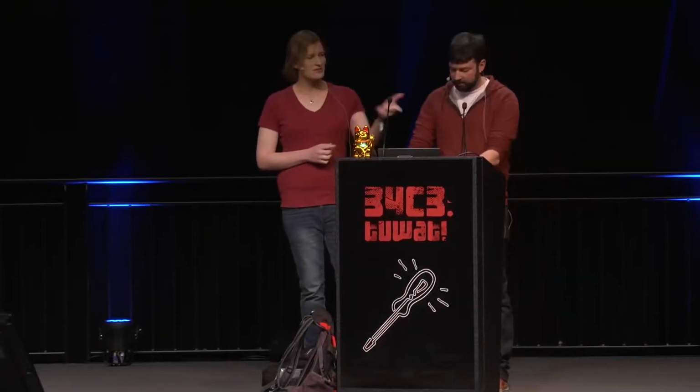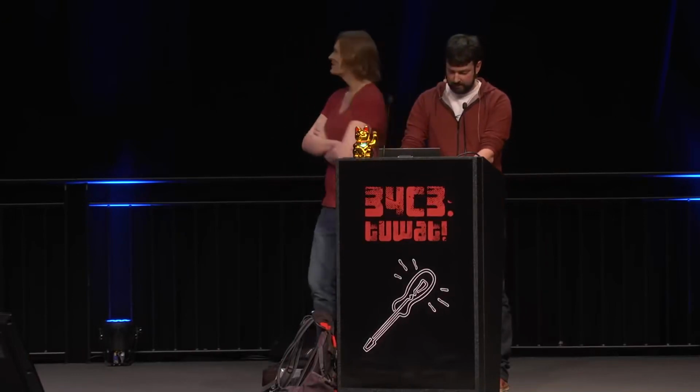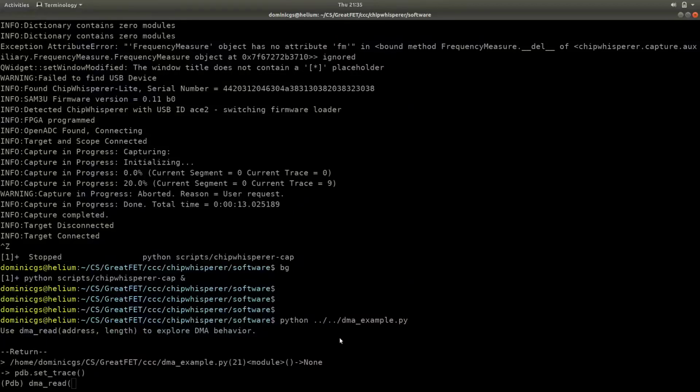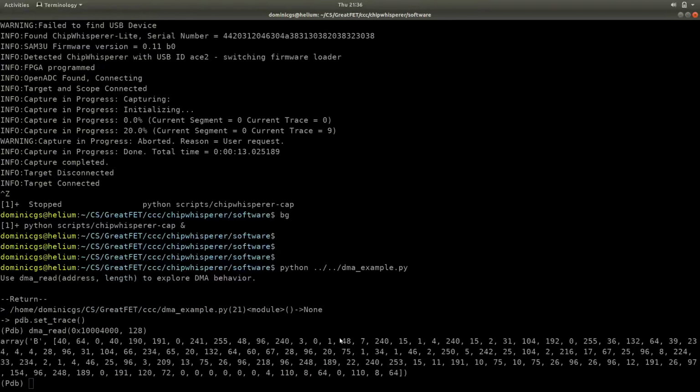And I'm specifically using LPC4330 microcontrollers. This is not something you're going to see in every DMA controller, but on a lot of the embedded DMA controllers, error checking is a premium feature and is left out of a lot of the individual peripherals that use DMA. So the CPU itself may execute transactions on the bus and get notified if it requests memory that doesn't exist. A lot of times a DMA controller will have absolutely no error checking, just because there's no way to handle errors when hardware is executing them. So it won't stop transactions, it won't generate a fault, it won't generate an interrupt. It's just happy to do things like read all zeros.